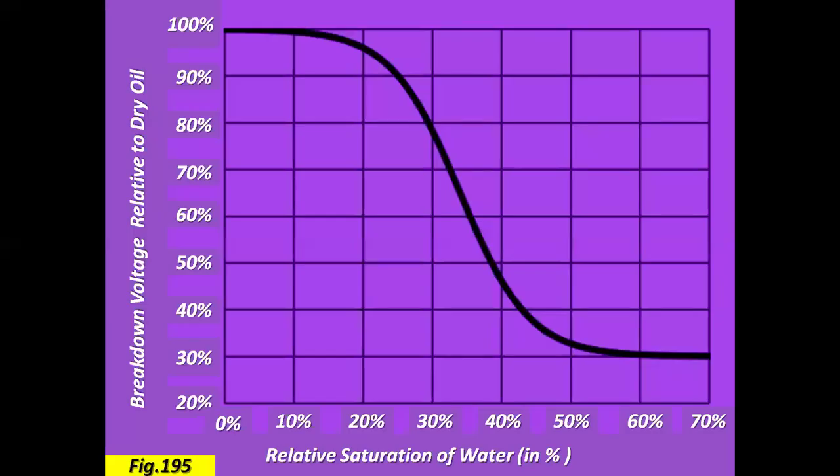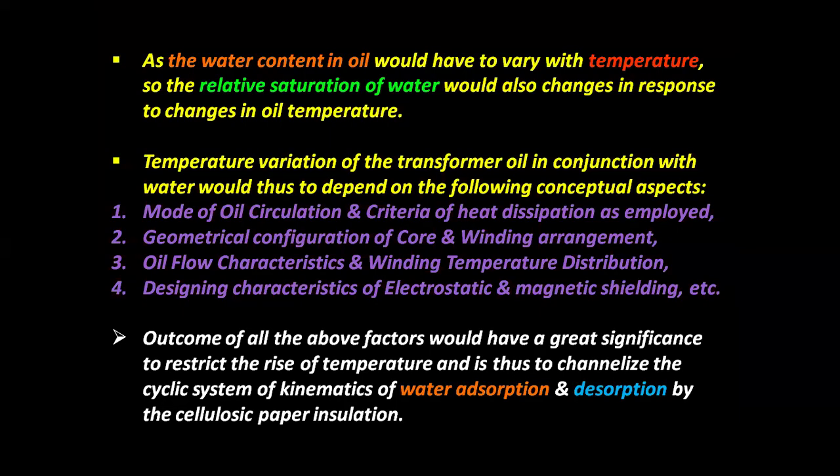Now, see the graphical interpretation: breakdown voltage relative to dry oil and relative saturation of water in percentage. As the water content in oil varies with temperature, the relative saturation of water would also change in response to changes in oil temperature.